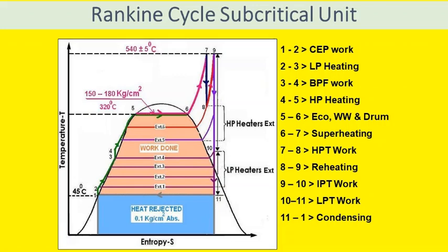In the condenser we have circulating water continuously flowing through it, where heat is taken away from the exhaust steam to make it again in the form of water or condensate, and that condensate is pumped back to the boiler successively by CEP and BFP.